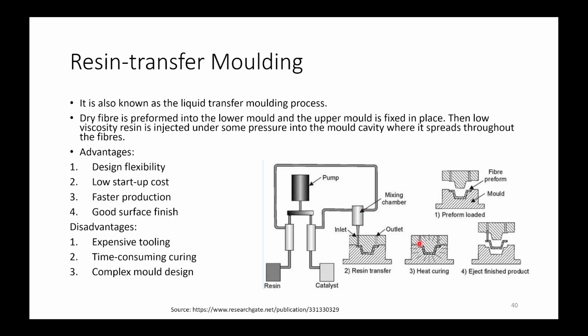After that we'll be curing it. For that we'll be heating, then the final product will be ejected from this die, and that's resin transfer molding.